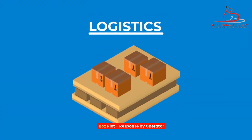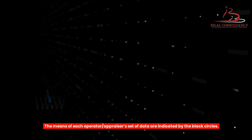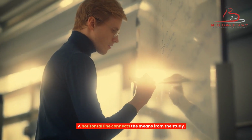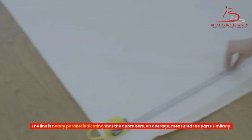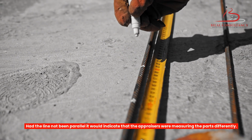Box plot, response by operator. The response by operator box plot can indicate if the measurements and variability are consistent amongst the appraisers. The means of each operator-appraiser set of data are indicated by the black circles. A horizontal line connects the means from the study. The line is nearly parallel, indicating that the appraisers, on average, measured the parts similarly. Had the line not been parallel, it would indicate that the appraisers were measuring the parts differently.